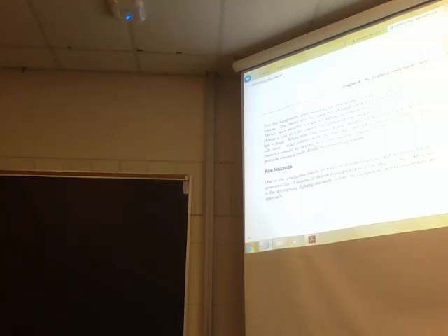Switches should be opened in a firm, positive manner to prevent arcing, like the fast make, fast break spring action. All portable electric tools should be properly grounded. Portable electric tools are mostly rechargeable now, but if you have electric portable tools, if they don't have a three-prong cord, it must say on them that it's double insulated.